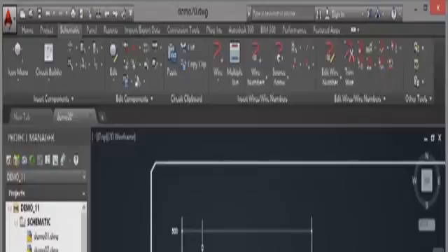And you don't have to go into each and every drawing and edit all of those one by one. You don't have to go and just revise the ladder numbers on one drawing. You can do all of them in one hit, like I've just done. Now, obviously, this isn't a very complicated AutoCAD Electrical project, so it literally took a few seconds to do that. If you've got a very busy project, sometimes that can take quite a while. So like I said, go get that cup of coffee, let AutoCAD Electrical do its work. When you come back, it's all renumbered for you.